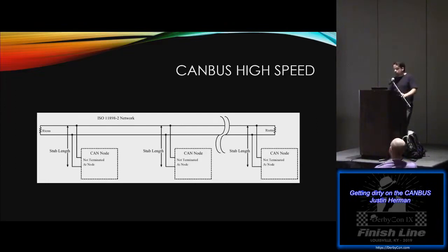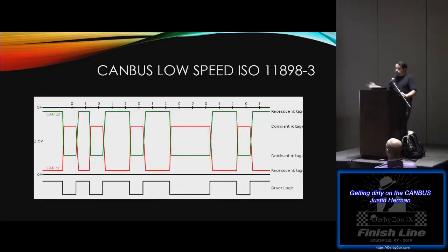With the low speed, you're talking about 30 to 125 kbits. So in low speed, you were driving individualized signals which are closer to 5 and closer to 0, and inversing them. Now that time for that collapse of the signal is the reason why we have to slow down the data transfer that can actually occur.